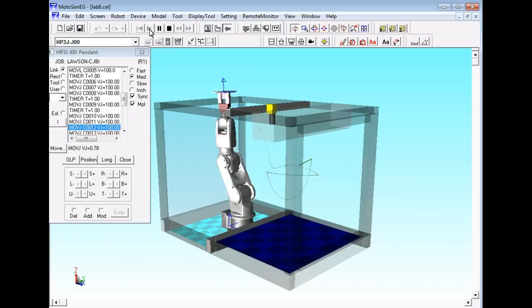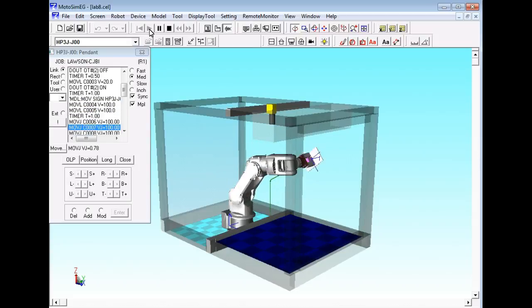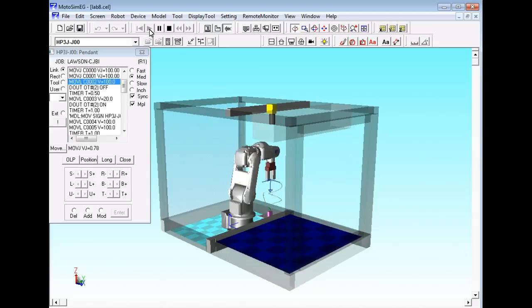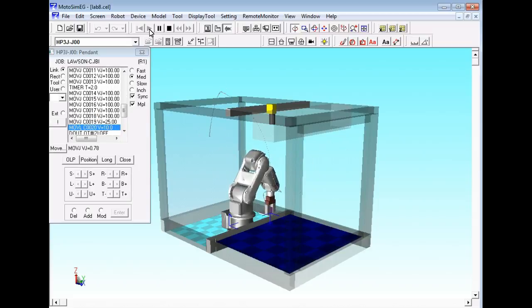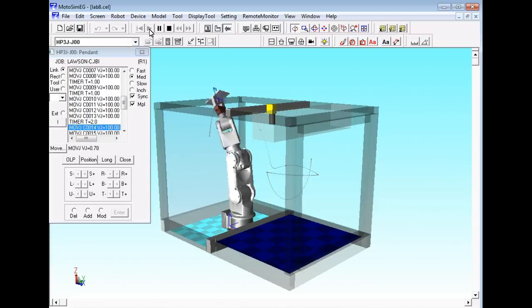Mercedes down there has almost 1,300 robots. And you can imagine how many people it would take and how long the robots would be offline if they had to reprogram those robots online. So most of your big applications, your programs are actually developed on a simulation, and they get all the bugs out of the simulation. They make sure it's no collision.